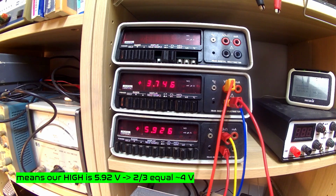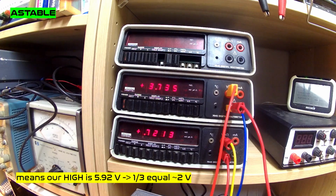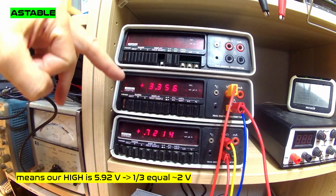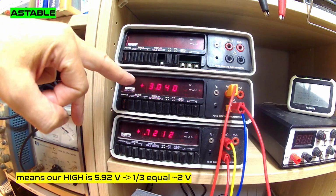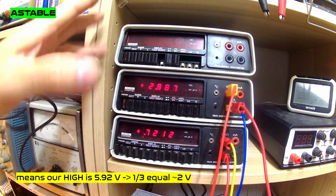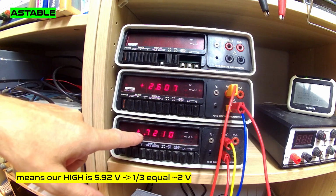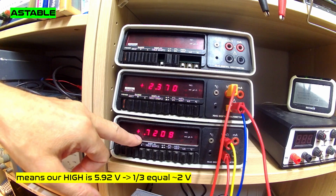And at this moment we should see the LED and hear the buzzer. Right now we see how the internal transistor discharges this external capacitor, and then when it goes to around 1/3 of VCC, it changes the state of the output.